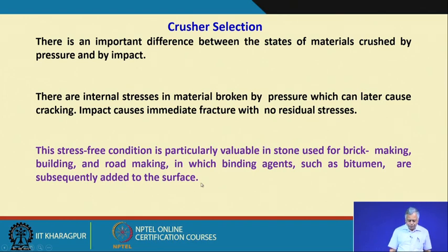Why? Now, if I use pressure energy for stone crushing, what will happen? There will be residual stresses and the particles may have internal cracks.